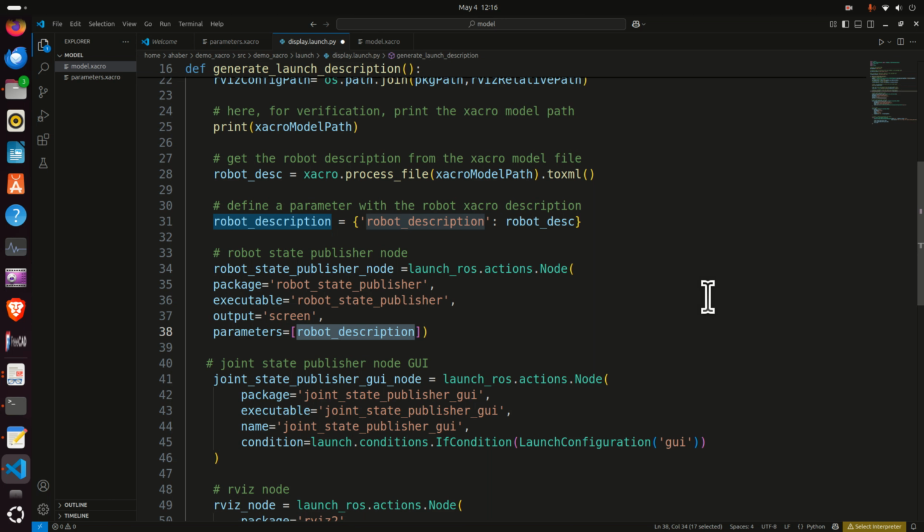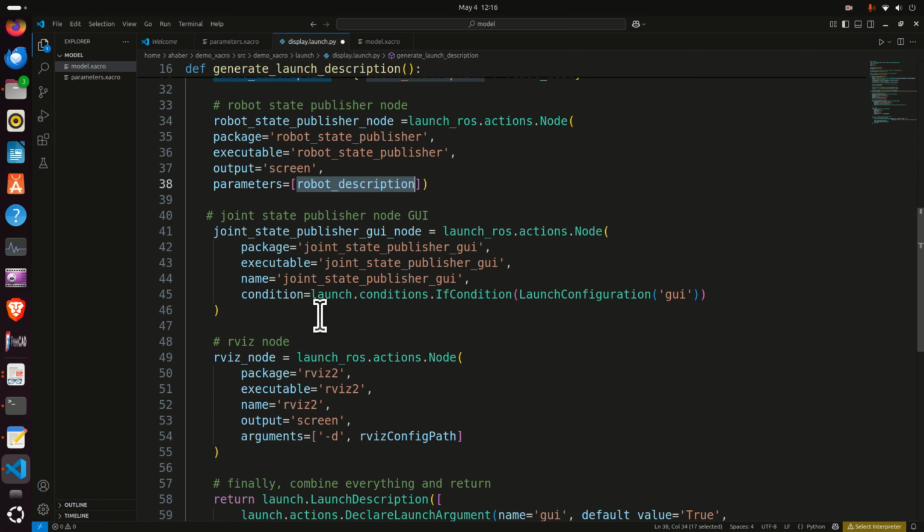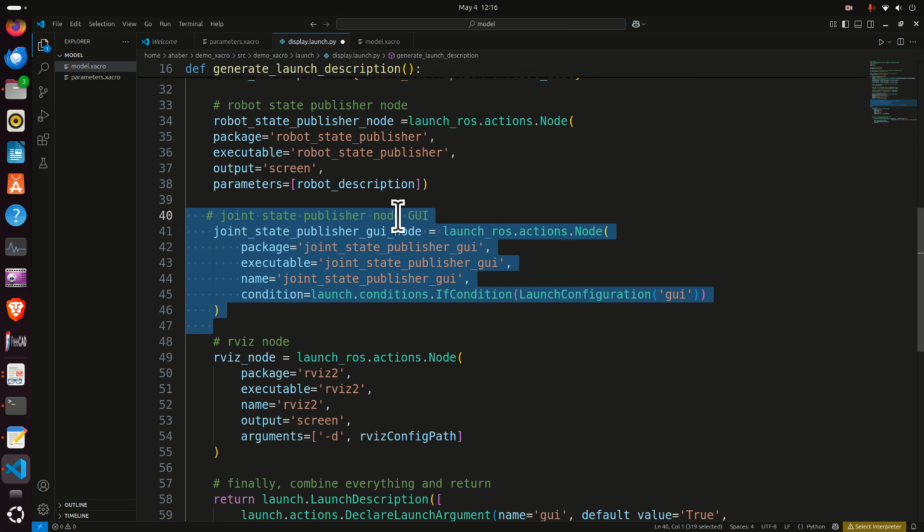transformational coordinate system such that we can display this information. That information is passed through the TF topic, and RViz uses this information to display the model on our screen. However, we also need an additional node, and that node is being used to set the robot angle of rotation by using the graphical user interface, and that's precisely that slider at the beginning of this tutorial.